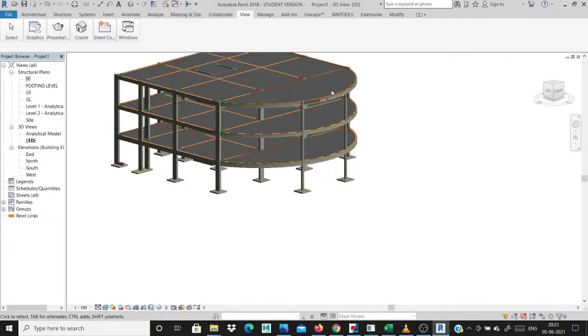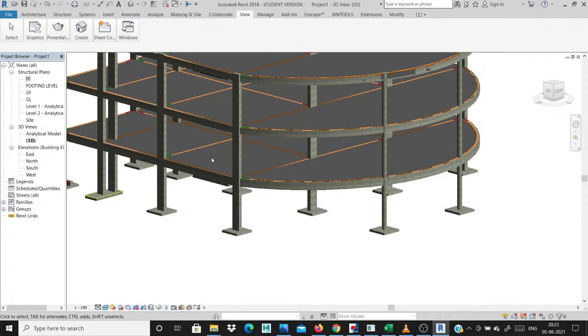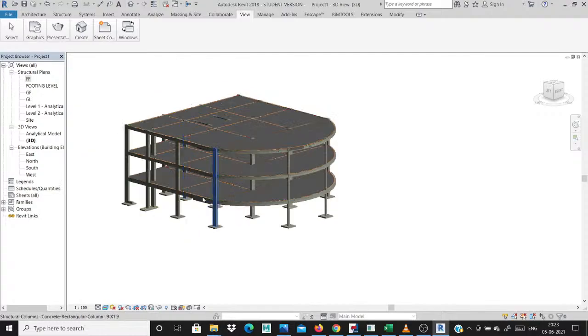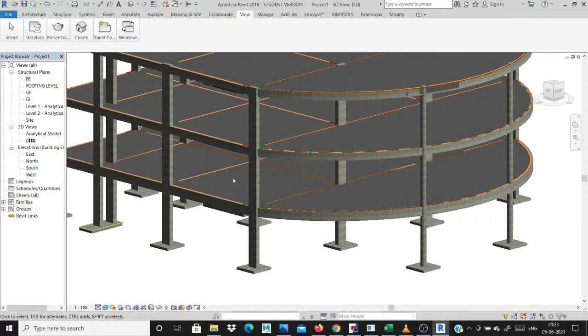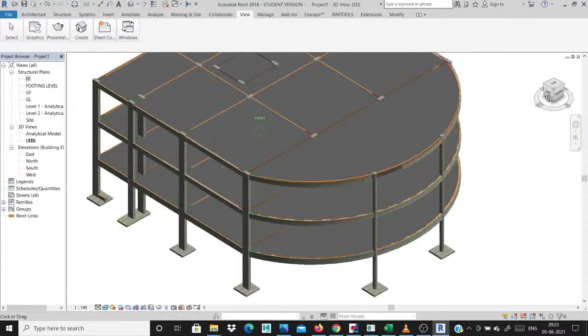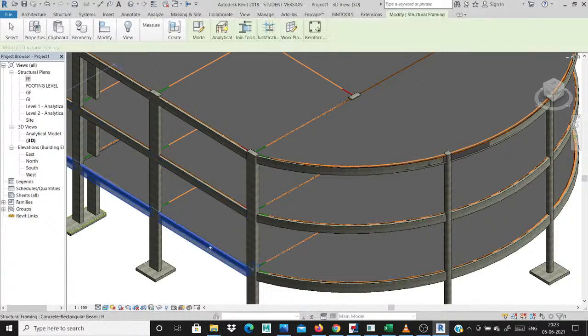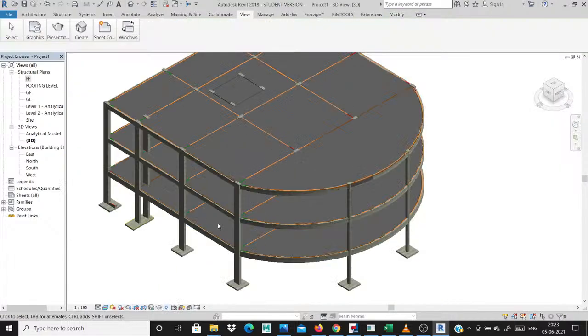See this, I simply created the different types of footings and other works. You create the staircase also, RCC staircases. How to create it: I need this area and how to edit these floors. See this, I need this staircase area for this area. Simply select these floors. Okay, first of all simply hide this, select this. How to create the staircase for this area.